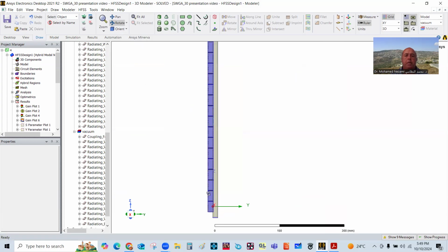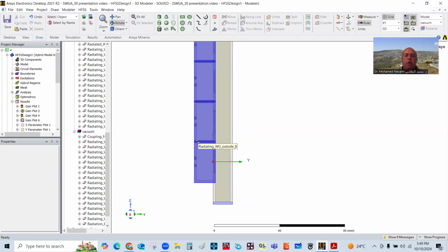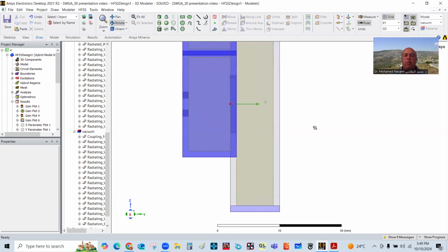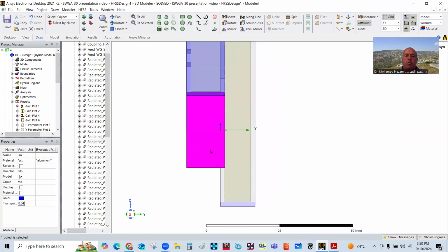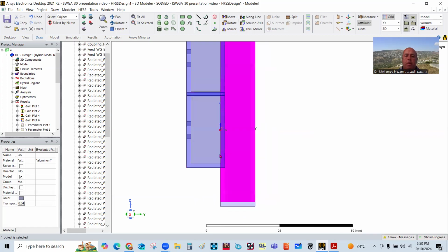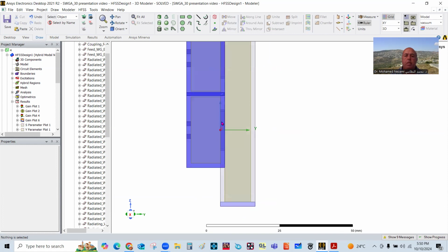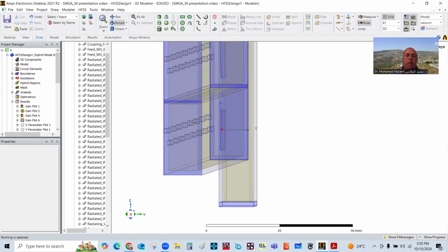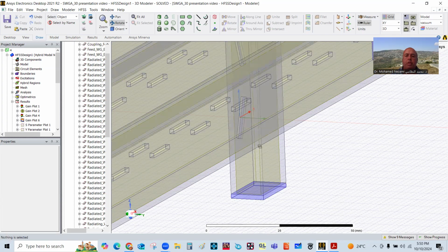But basically what you need to do is overlap both the feed waveguide and the radiating waveguide. This is the first one, okay? So you combine them with the same thickness so that you can hollow out the feed slots in here. And of course, the radiating slots are on the other side of this. And that's what you see here.